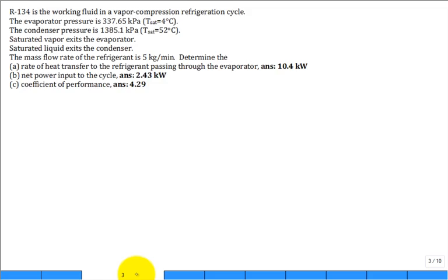All right, so set up and solve a problem. You read the problem carefully and organize the information. It's very similar to the problem that we solved last time, but it's not a Carnot refrigeration cycle. It's a vapor compression refrigeration cycle. The same working fluid. The pressure of the evaporator is the same, meaning most of the phase change is happening at 4 degrees C in the evaporator.